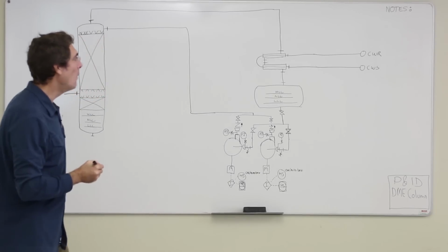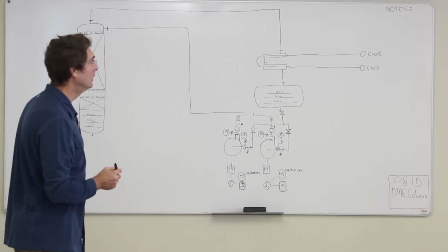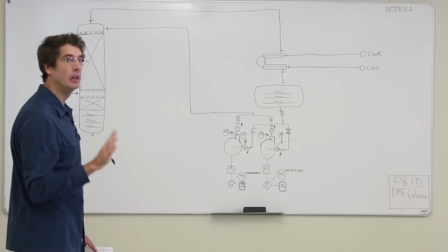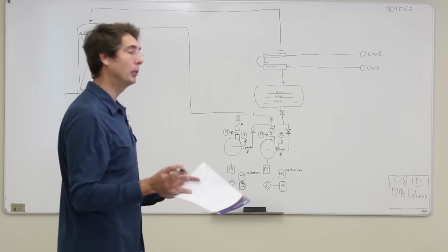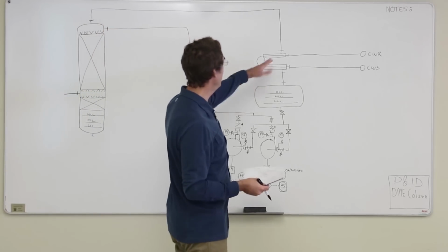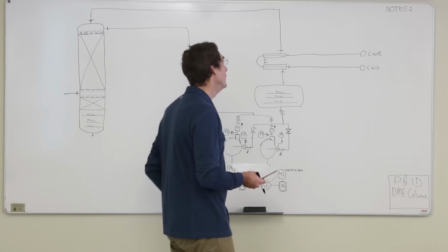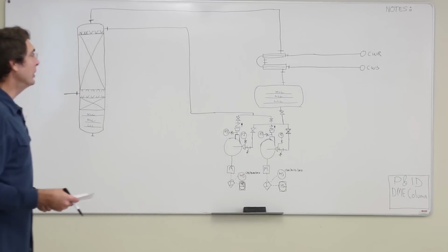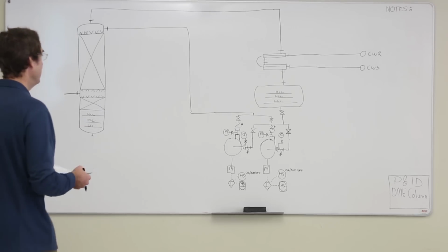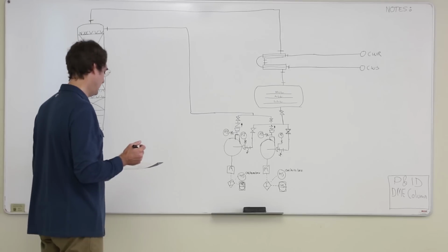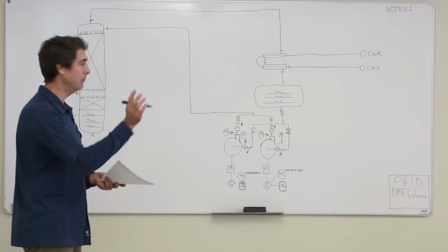It did occur to me this morning, and you guys probably thought about this too, that we might be able to use an air cooler on these towers. That would be an interesting design because we're trying to make this very small scale and very modular. An air cooler would use some electricity because you need a fan turning, but it would possibly reduce some of the piping and complexity of the overall design. So if I had to go back and redesign this process, I'd be seriously looking at using air coolers, because we're certainly at temperatures that could make that work. We could put the air coolers on top of the container and have a fan that blows up through them.